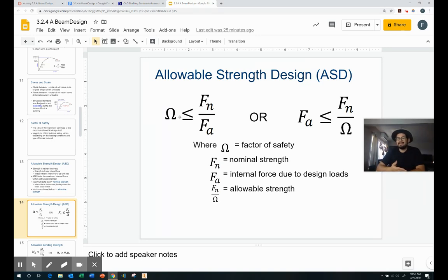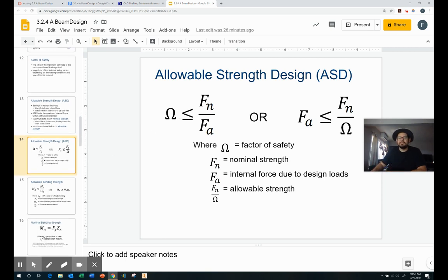But when I say that the design load, meaning the amount of people that can even physically fit into this box, assuming they're all 6 feet, what's the weight that they're going to load into this elevator? It might be 4,000. So 5,000 divided by 4,000 gives me 1.25. And so my safety factor is 1.25. So what we want to say is the safe range should be that many times greater than what the design condition is going to allow for. All right. So hopefully it'll make sense when we start getting into it a little more.